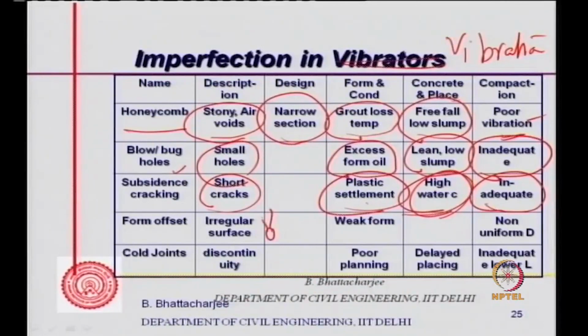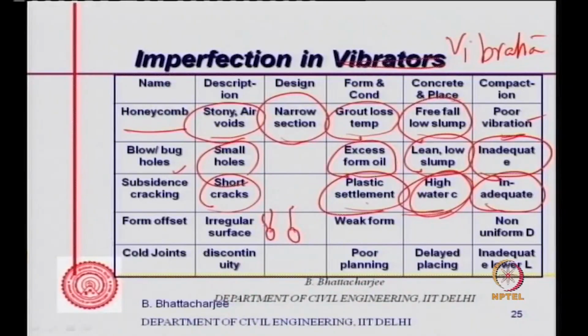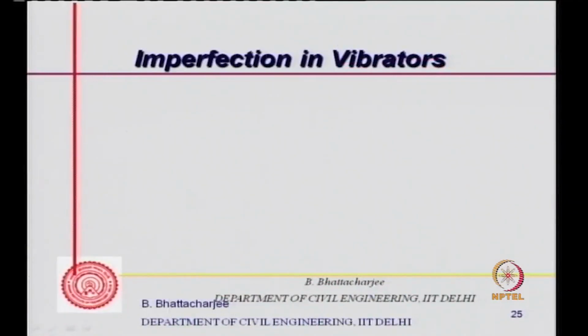Over reinforcement, sometimes you might see, just over the reinforcement, this is the concrete. In fact, it might look something like this. So the top concrete surface might look like this. There is a crack, and then there is a subsidence, there is a crack, and so on and so forth. So you have reinforcement here. This is a concrete surface. Let me draw it just here. It can look like this. Then there's a crack, then there's a crack. Quite often, this could be over reinforcement and then several other situations.